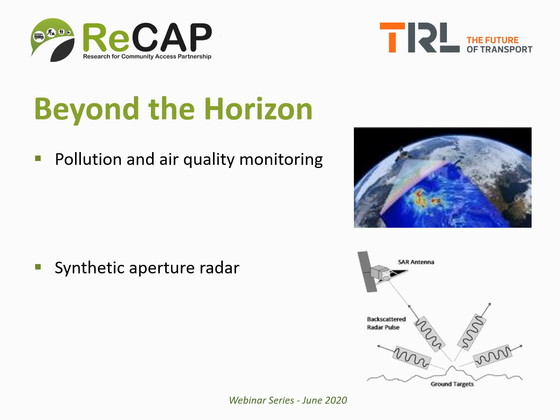Synthetic aperture radar is an active mode of satellite monitoring, whereby radar waves are dispatched from a satellite and their return is monitored by a sensor. This creates a point cloud that can provide information on materials and terrain. As radar is sensitive to the physical structure of the surface, it could be possible to determine pavement characteristics such as roughness or incidences of flooding.